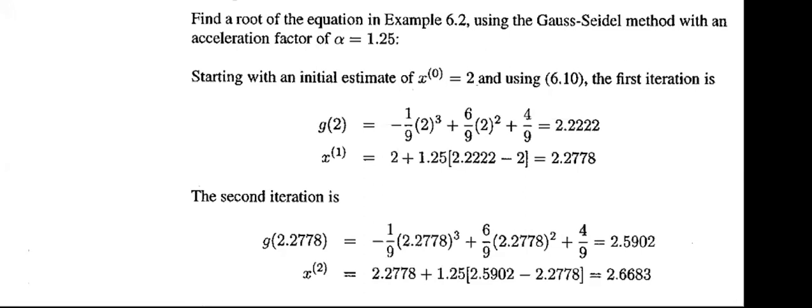Have you got the idea of the Gauss-Seidel iterative method for nonlinear equations? Student: Yes, sir. The answer comes in 7 steps this time. Okay, might be one step fewer, or sometimes it may be faster. And regarding that acceleration factor, it might be mentioned. It is 1.25 for this case. It might be 1.4. It might be 1.5. So it will be given in the problem information.